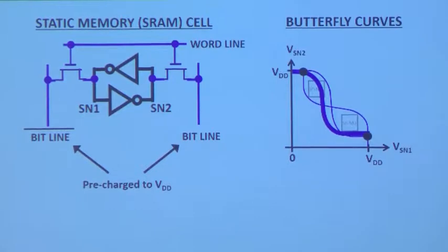But what happens with an asymmetric change in the threshold voltage for one inverter versus another? You can shift one of the voltage transfer curves this way. The other curve would shift in the opposite sense. So you can see that this margin here, by which you can shift left and right or up and down, the noise margin, is degraded.